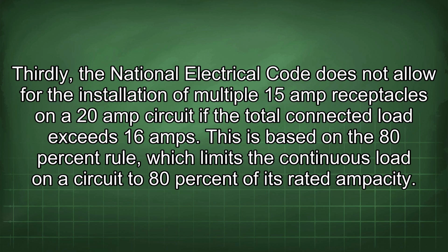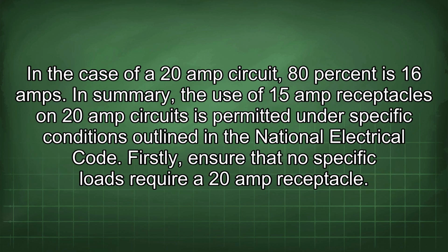This is based on the 80% rule, which limits the continuous load on a circuit to 80% of its rated ampacity. In the case of a 20 amp circuit, 80% is 16 amps.